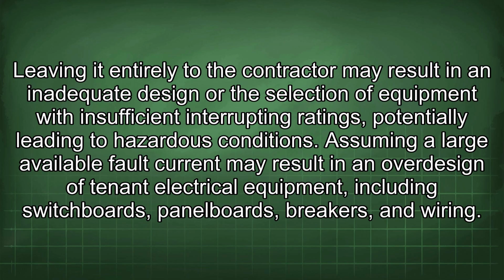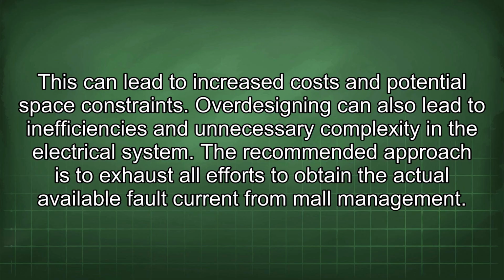Assuming a large available fault current may result in an over-design of tenant electrical equipment, including switchboards, panel boards, breakers, and wiring. This can lead to increased costs and potential space constraints. Over-designing can also lead to inefficiencies and unnecessary complexity in the electrical system.